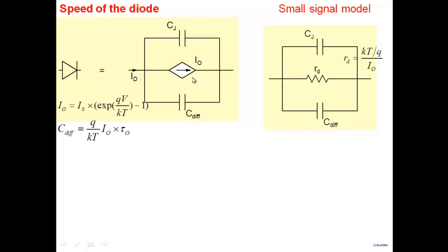You want current to be determined through this, because remember, rectification is coming due to what? The current in the forward direction is different from the reverse direction, right? But what about a capacitor? A capacitor conducts equally well in both directions. Whether I apply a positive voltage or a negative voltage, current flows in both. So it destroys your operation here.